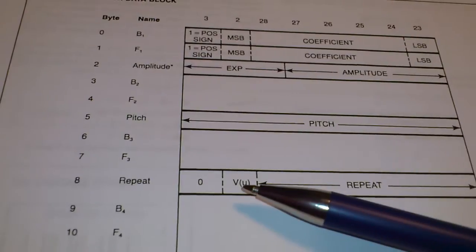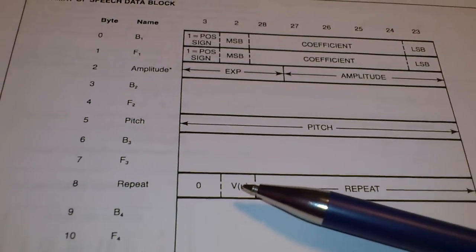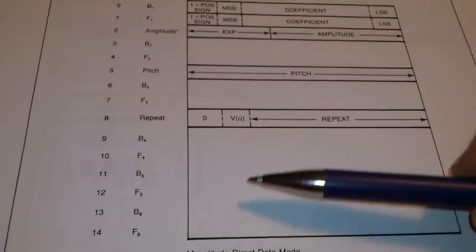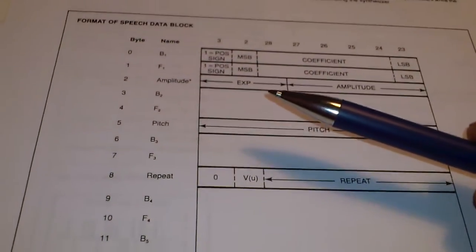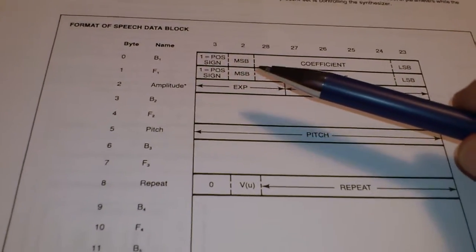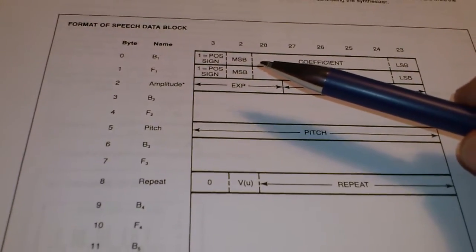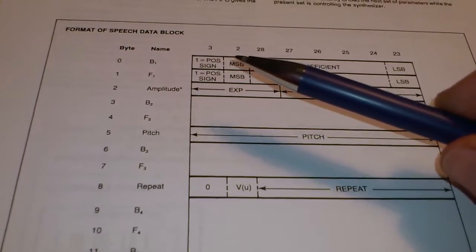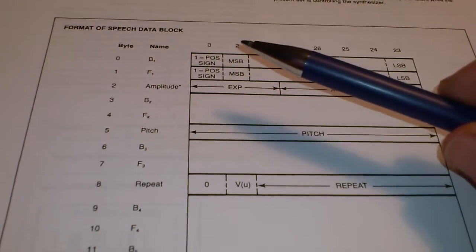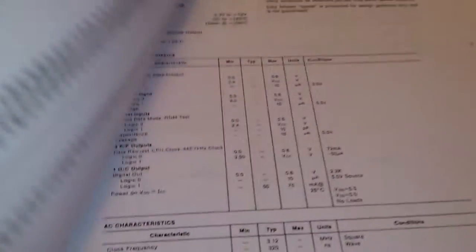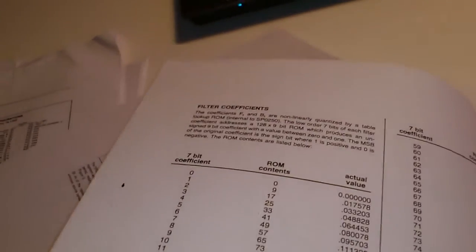This bit is telling you if you're using it voiced or unvoiced, as I explained before. And those here are just all these coefficients, which are coming in with, as I said, 7 bits of coefficient and 1 sign. And these 7 bits are approximated with a ROM internally to a 9-bit value, which is basically just a linear approximation. And the content of this ROM is also in the datasheet here. It's that kind of table here.